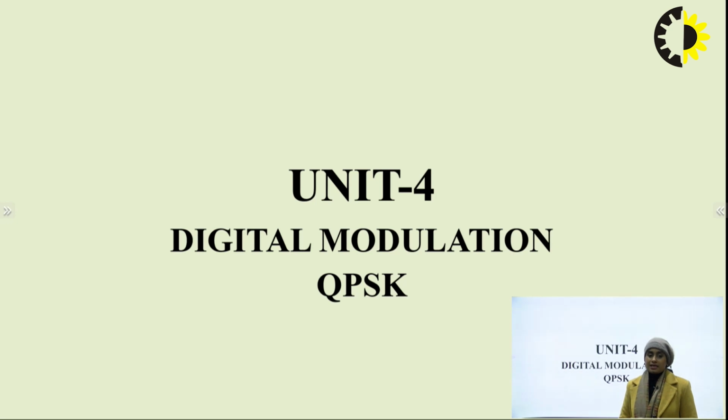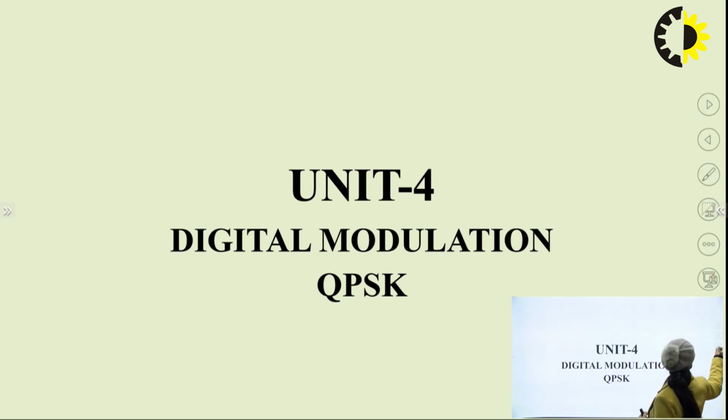Right. PSK has various different variants. Like in the previous lecture, we have studied BPSK, binary phase shift keying, which is the simplest form of PSK. It uses one bit at a time. That is, the symbol is composed of one bit only. That single bit is responsible for varying the phase of the wave, or at the receiver side, by reading the phase variations of the modulated waveform, what we can predict is just one bit at a time, right?